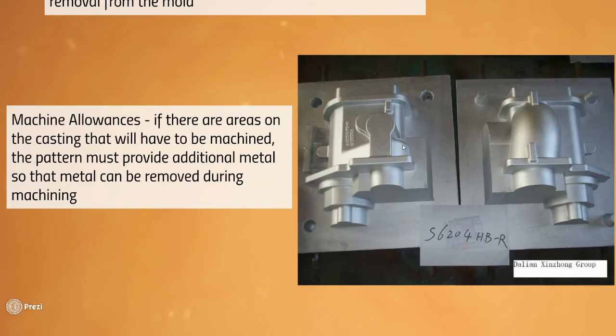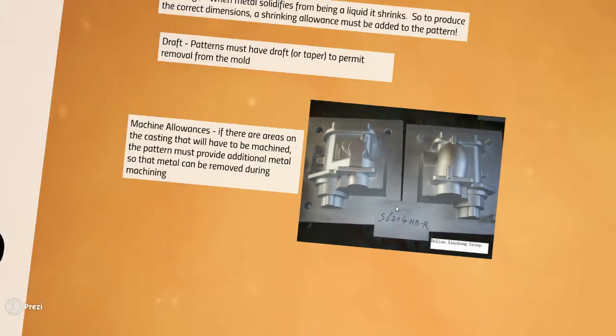Okay, so these patterns will actually have to be larger than what your actual product is supposed to be, because you need some room to machine some of those surfaces and make them extra smooth.